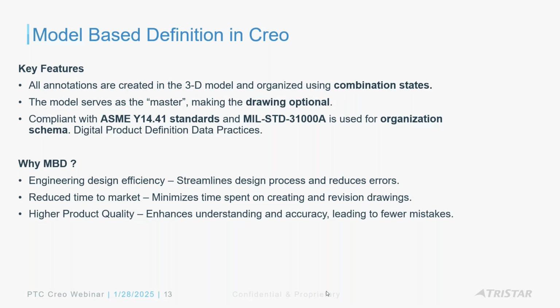But we are making sure that it's also compliant with the ASME Y14.41 standards, and the organization schema or the namings for the combination states is based on the MIL standard 31000A, right? They have a section on digital product definition and data practices.